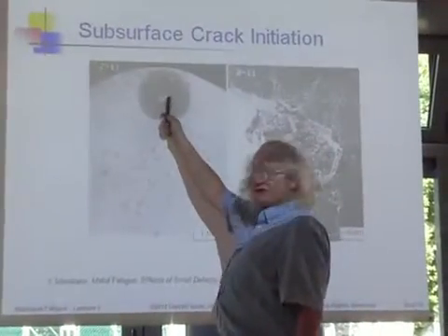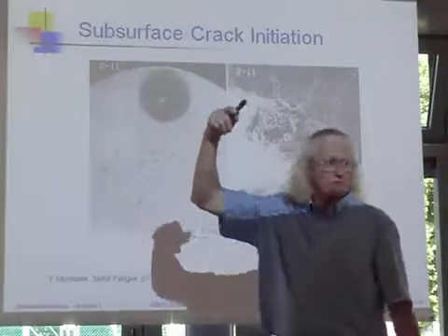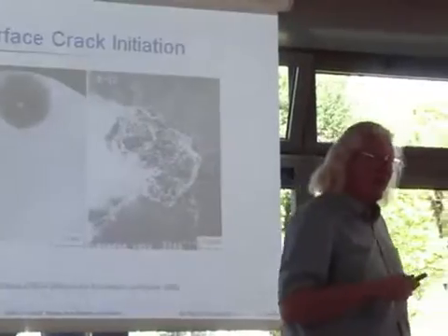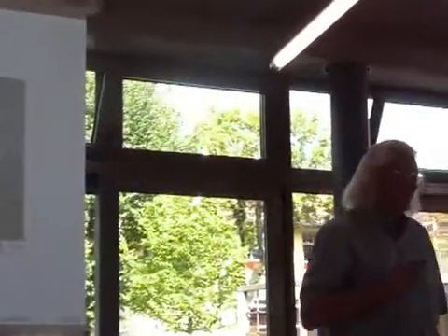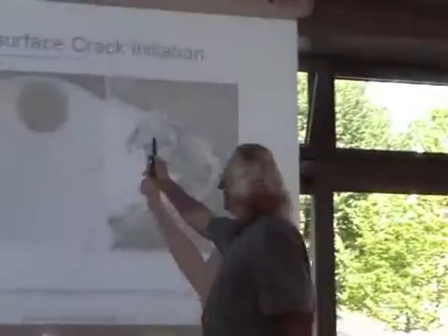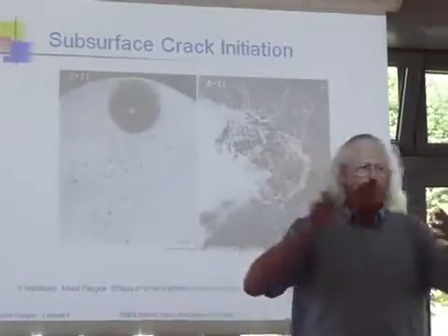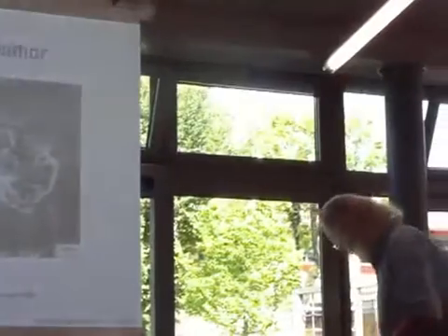and in 1990 he showed a slide that kind of looked like that. And he said, there's been this tremendous progress, and he showed what the fatigue limit changed, and it went up a lot. And then he said, here's what we sell today, and he put up a blank slide. Or what appeared to be a blank slide, and he said, look what happens. So these problems all have to do with the size of the crack nucleator. The size of the crack nucleator controls what the fatigue limit is. All right.